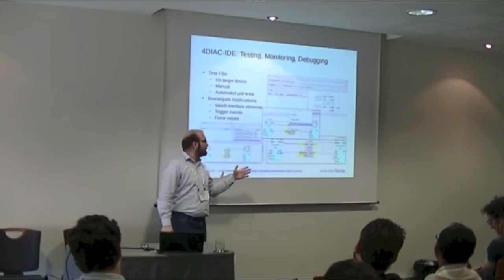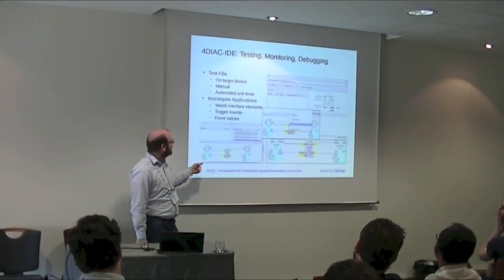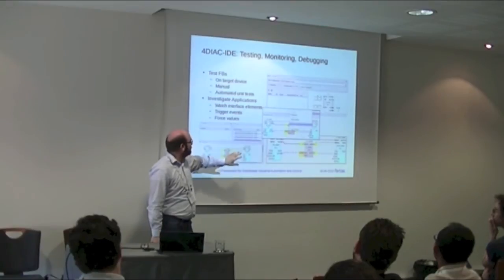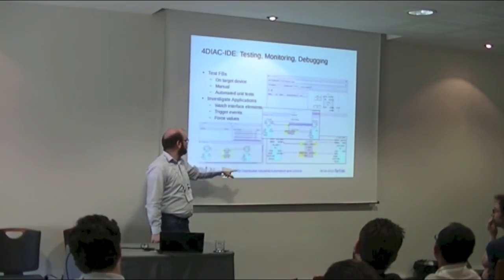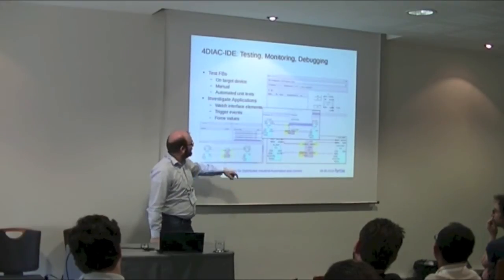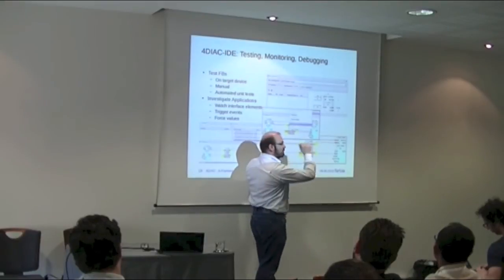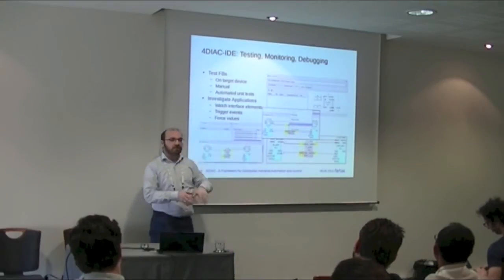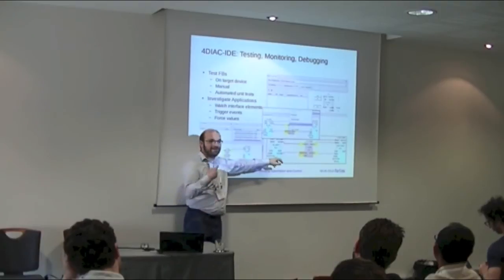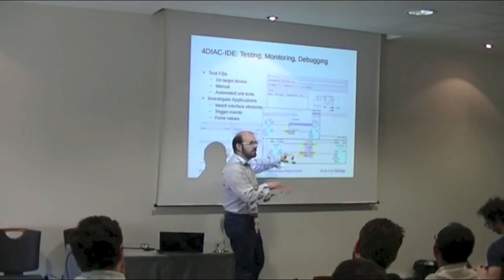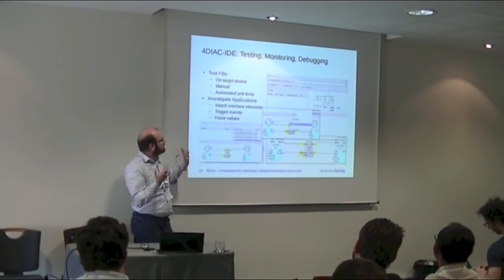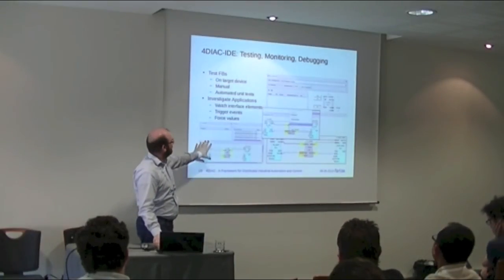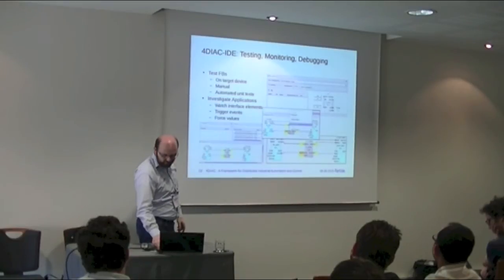What's also very important, and this is a very recent feature, I think we have had it for half a year now, is that we can go online from the tool to our devices and say, I want to monitor this function block: give me how many events have been received, how many events have been sent, how are my data values. Maybe trigger an event, as a test if this functionality is working, or, what's also very important, force a value. Very often a part of the system is not available or produces incorrect results for your test. So you need to set it to a fixed value which is not changing during execution, which in industrial automation is called forcing. For industrial automation it's a typical feature, and we are very happy that we have it. It cost us quite some implementation effort.